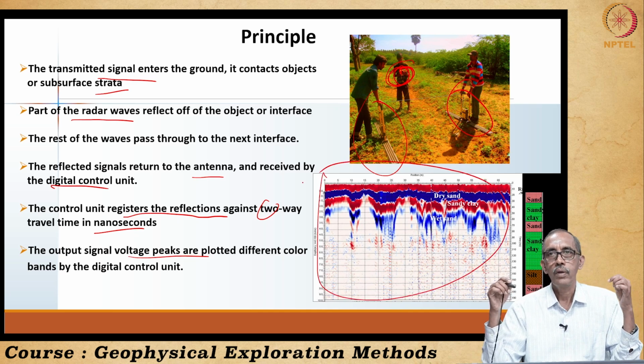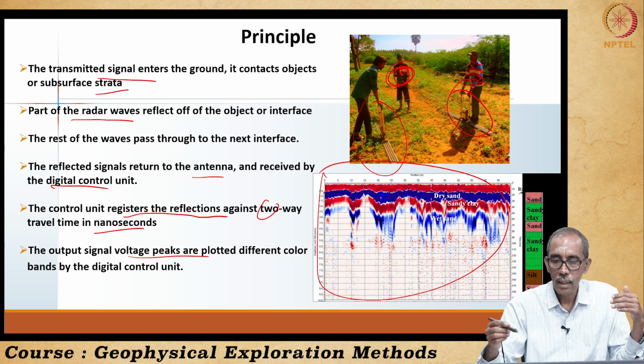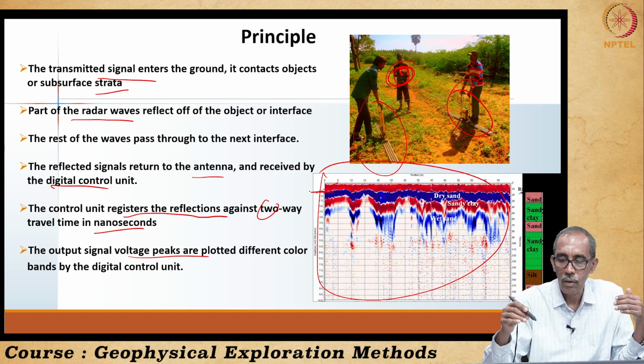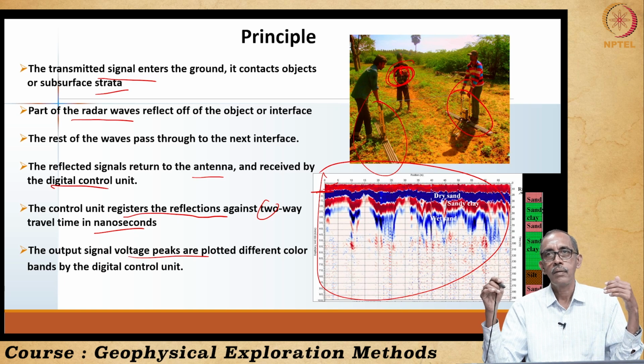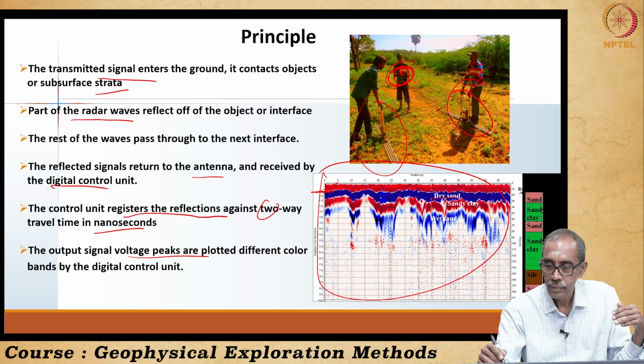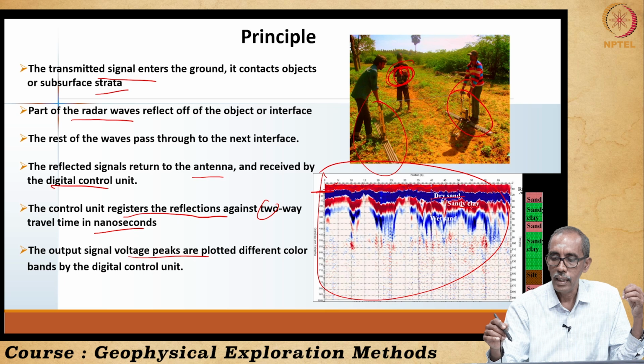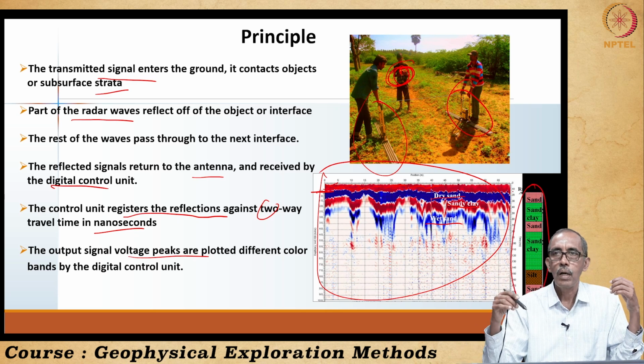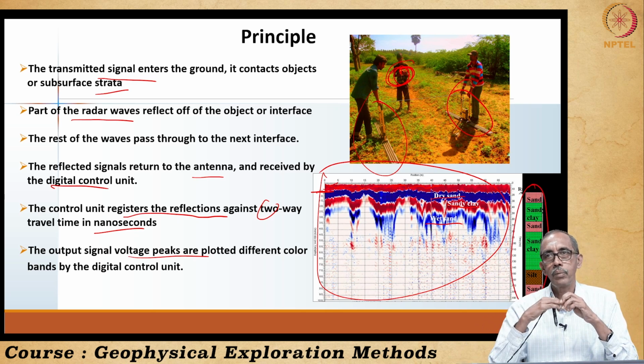So, here we have color bands of radar signals. Here too, the top is the surface radar waves, which are considered noise. Only from here is the ground surface. These color bands indicate the presence of different subsurface layers. Here, fortunately, we have interpreted them as dry sand, sandy clay, and wet sand, right. This is how we have interpreted it side by side. We had also drilled a small borehole, and we have cross-checked our interpretation with that, right.